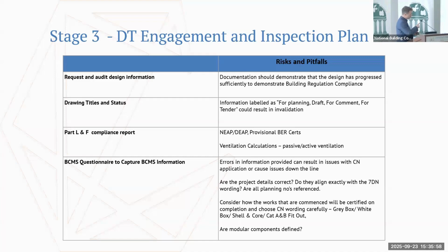Any specialists that we have early on, examples being like a piling designer specialist, we should be capturing ancillary certificates from them now. So it's been touched on, and I'll be touching on it again. We have the SD for specialist designs pre-commencement. You have the SC for designs post-commencement. So anything here that's going to be designed or specialists that are appointed for design at this stage, we should be capturing an SD.